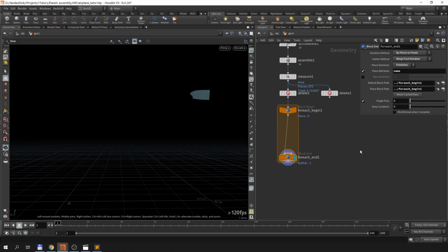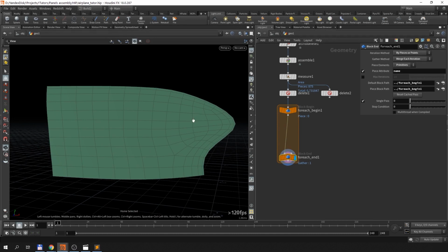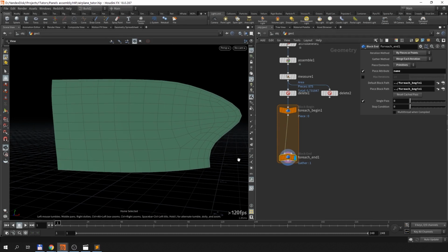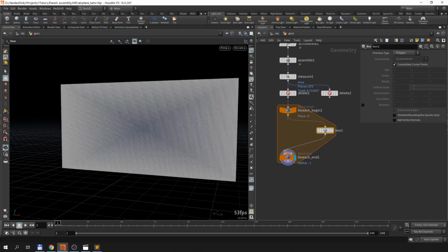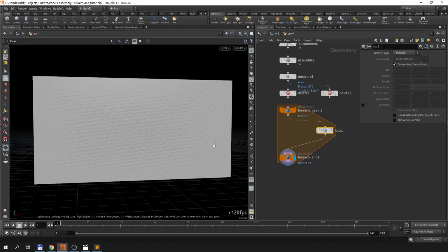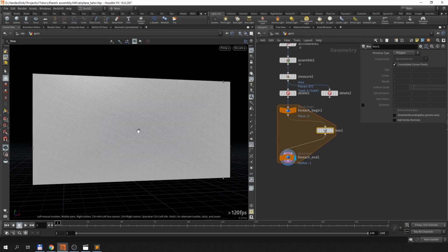So a couple of words about the splitting algorithm. We will take a separate piece, build a box around it, convert its edges to lines, extrude these lines, and then use this geometry as cutting geometry. The Box node has a single input, which takes the geometry to build the box around. Here's what we get, but we can see that we have intersecting geometry. As you can see, we have a couple of polygons on top of each other.